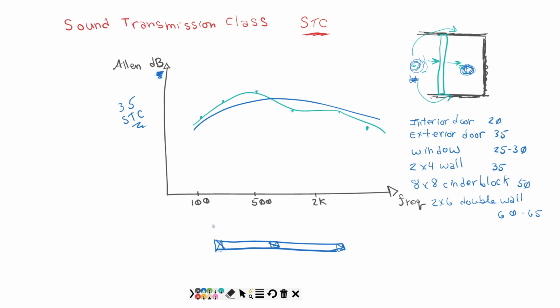Well, what we're going to do is we're going to make 2 walls. And we are going to separate these walls by maybe an inch or 2. So let's say 3-4 centimeters. And those framing studs going up are going to be offset, so they don't line up. Okay? And in this space, change color over here, in this space, because you got a 6-inch space in here, almost, you are going to put some fiberglass insulation.